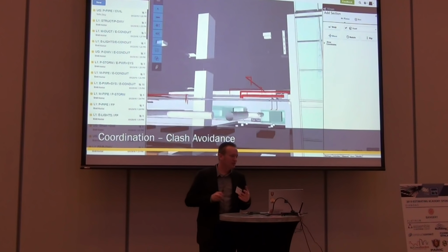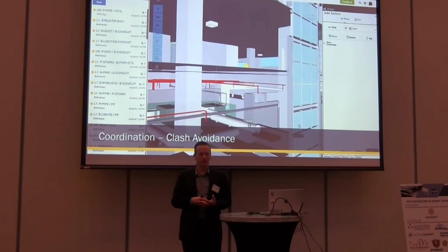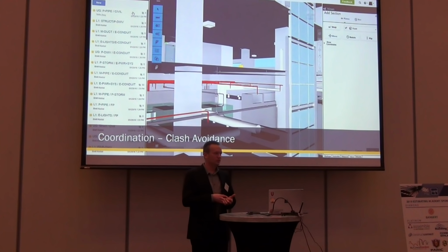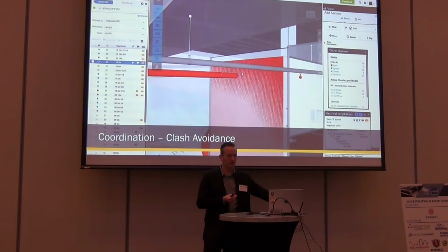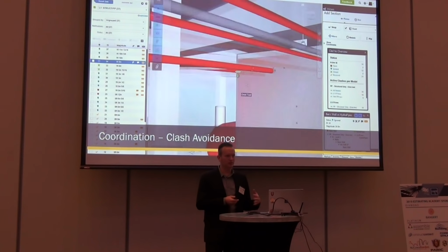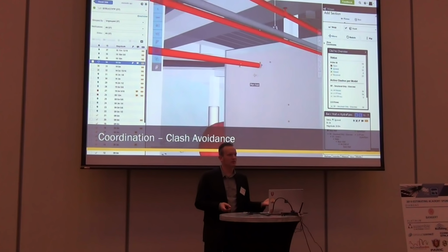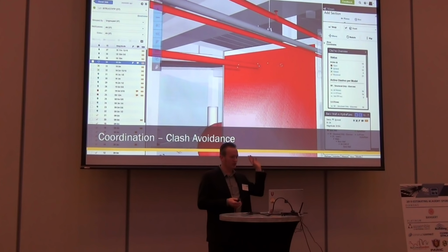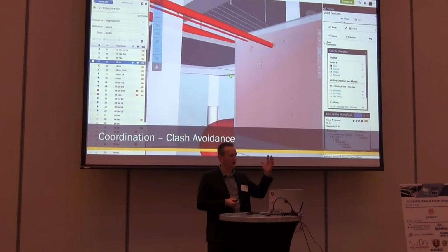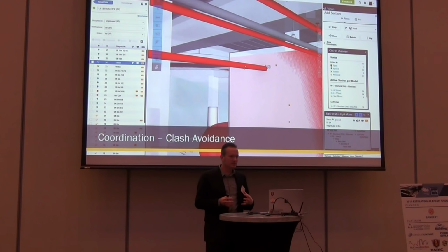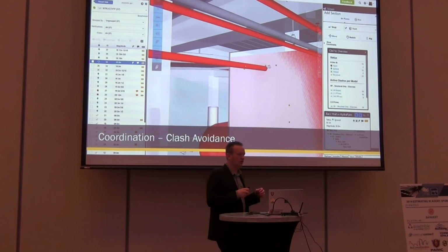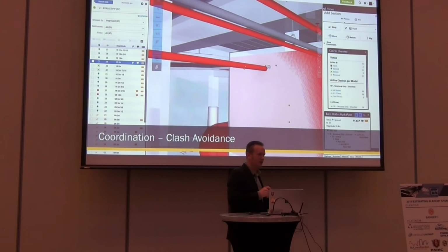So obviously BIM coordination is critical to what we're doing, back to communication. So what we try to do is we want to avoid doing clash detection until as far down the road as we can. We're really into clash avoidance for active design, right? If we know more about what's going on in the building, then we can design around it. So using scans or active models and pulling everybody onto the cloud, we can have them all actively designing in an environment where they know what's there and they can throw darts at the actual wall and not have to imagine where that wall is, okay?